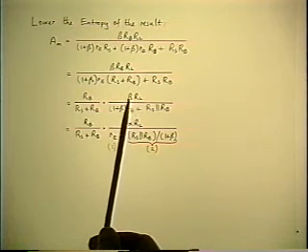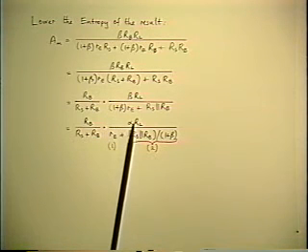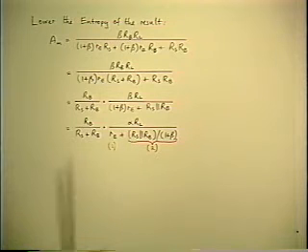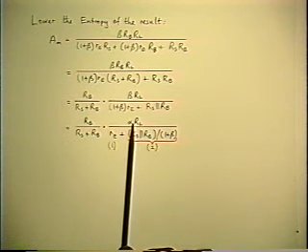So if I bring out front beta over 1 plus beta from this expression and call it alpha, which is the standard symbol for it, alpha is very close to 1 regardless of the value of beta as long as beta is large, which it's going to be. So numerically, alpha can simply be taken as 1.